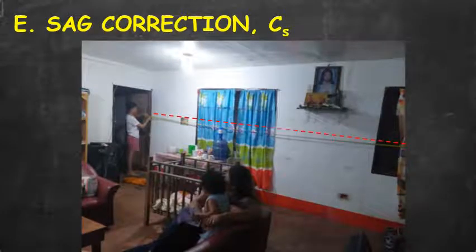So, second is a sag. So, this type of correction, so a tape is standard length which is fully supported under the standard pull or tension. So, the pull is maintained but every support is removed such that the tape is only supported at its end. So, it will sag because of its own weight.